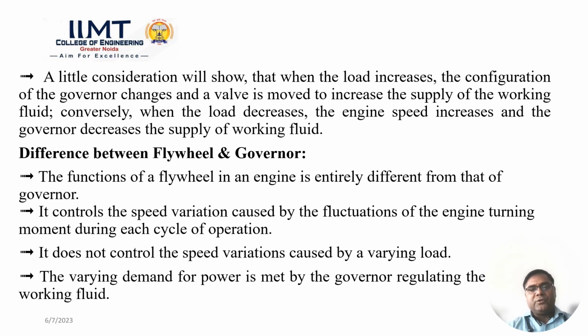You know that in a four-stroke engine there is one stroke that is called the expansion stroke. In this stroke you get the energy, and for the remaining strokes you do not get the energy. So the excess energy is stored in the flywheel in the form of kinetic energy, and it is used for the remaining strokes, which are not given the energy.